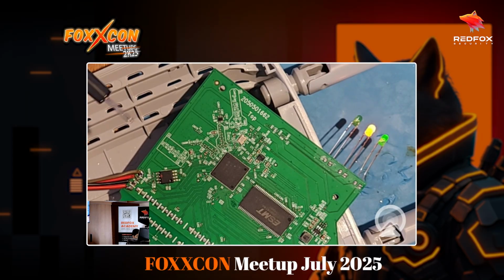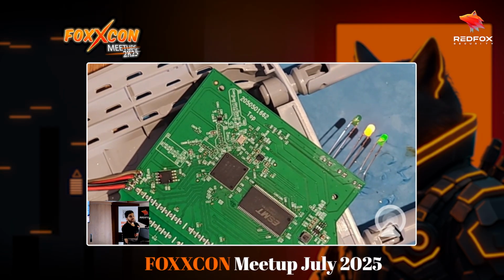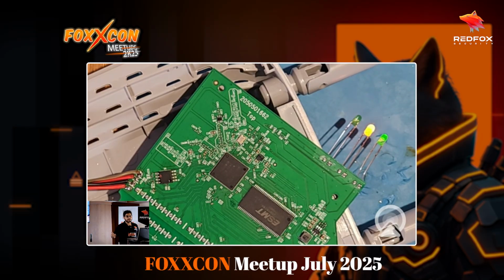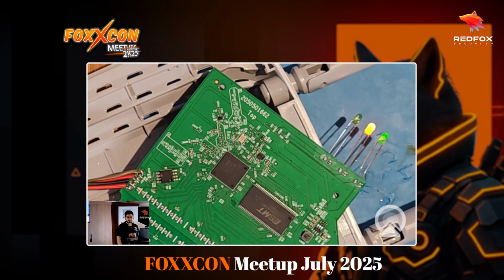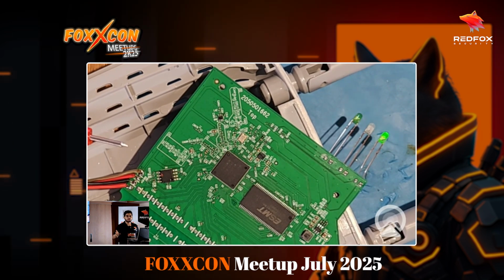All right, so that can also be measured in a similar manner to how we found VCC. As I was showing you guys, you might have seen one pin pad was fluctuating. Whenever you're transmitting data, it shows up in bytes, ones or zeros, which means the current will be fluctuating. So inherently, the fourth pin that I was testing, which showed up as fluctuating data, is your transmit pin.